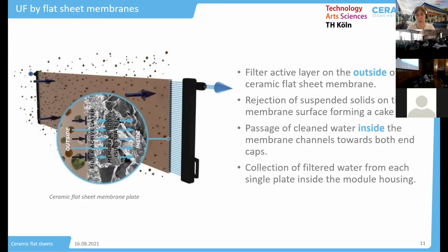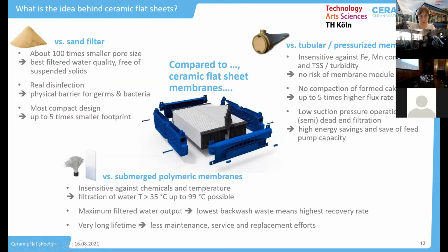These filters are working with an active filter layer outside of the ceramic flat sheet membrane. The suspended solids are rejected outside the membrane and the clean water is sucked into the membrane and transported by the end caps out of the system.